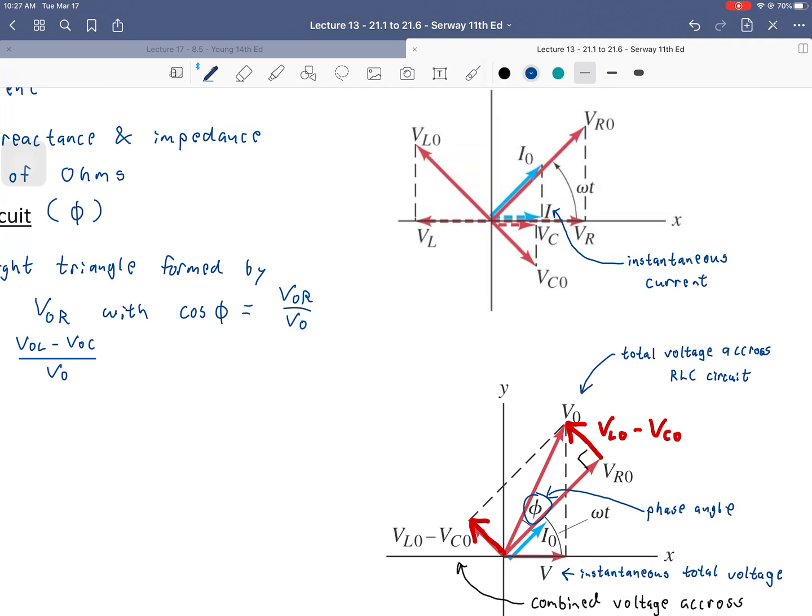But here's the thing, that's not entirely true, because the material properties don't tell the whole story for the inductor and the capacitor, because their reactance, and this was a big part of the first half of this lecture, is frequency dependent. So the phase angle depends on material properties of the inductor, the capacitor, and the resistor, and the frequency.